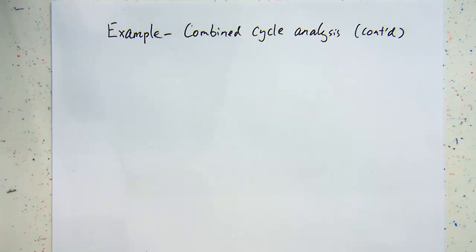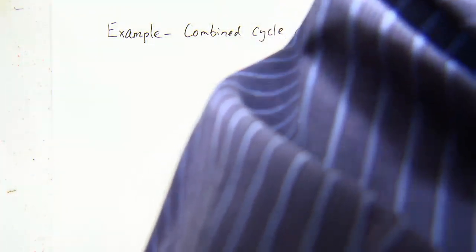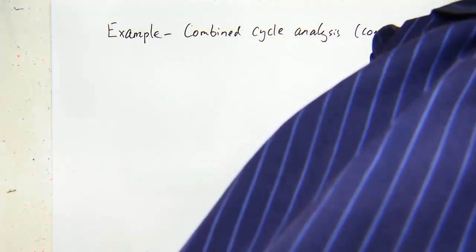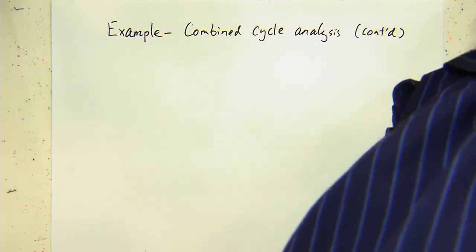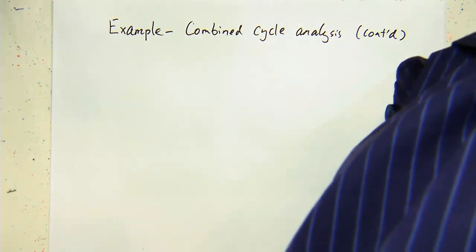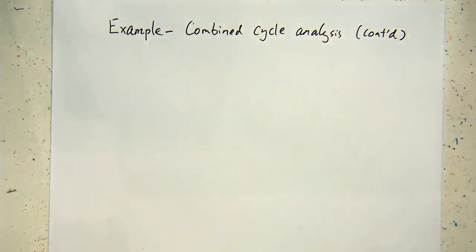All right. In the last lecture, we started this combined cycle problem. As mentioned, the combined cycle is a steam power cycle combined with a gas turbine power cycle. Essentially, the two cycles for this particular problem are all running on their basic design, and they are coupled through this heat exchanger, which is used as the steam generator for the steam cycle.